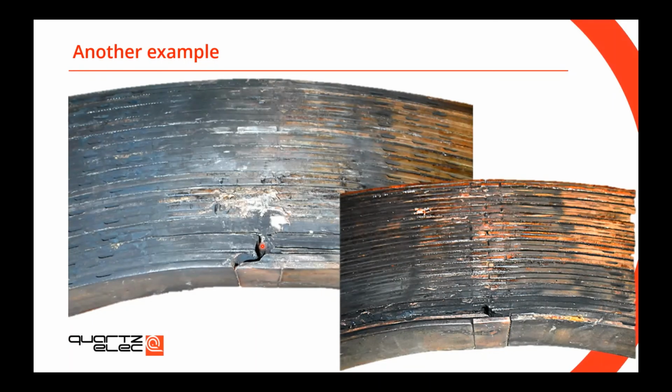And just to confuse you even more, that was the longest coil. So this operator didn't see a problem with the rotor and rotor's vibration because that was the longest coil, so there was no influence onto the vibration, and yet they ended up with a serious problem and an earth fault. So yes, we did say that location is critical, and we did say that it could cause vibration, but that one good example can prove that even with those assumptions, we can have serious problems with our rotors.